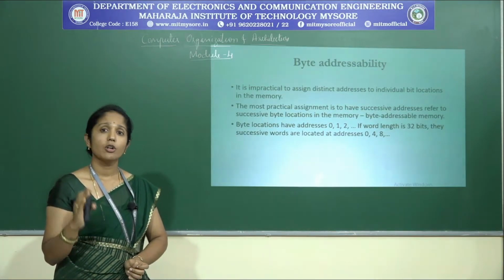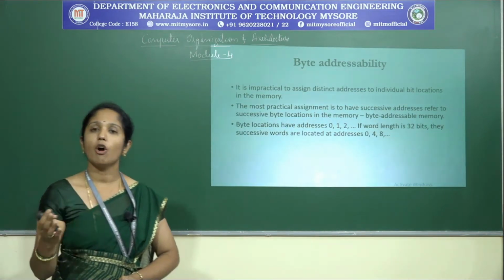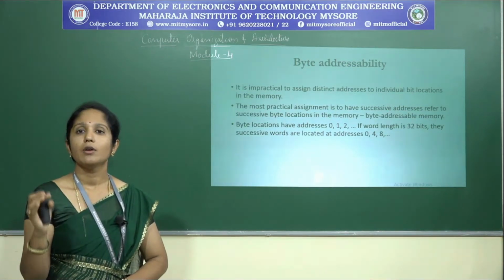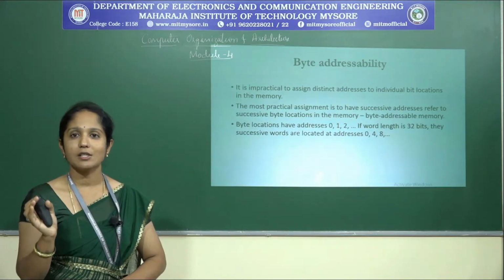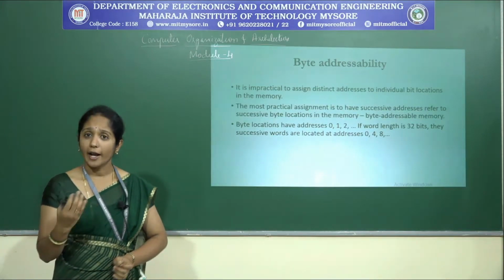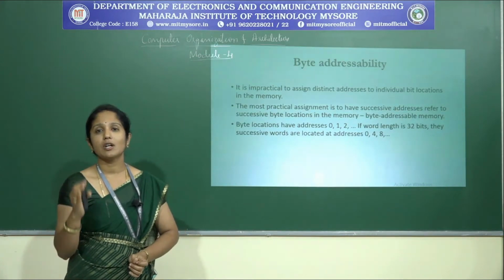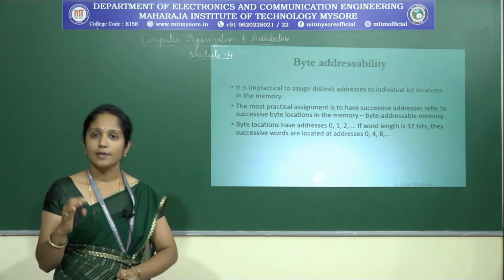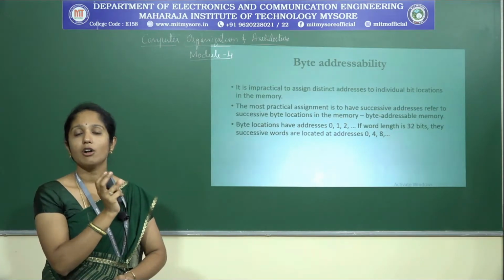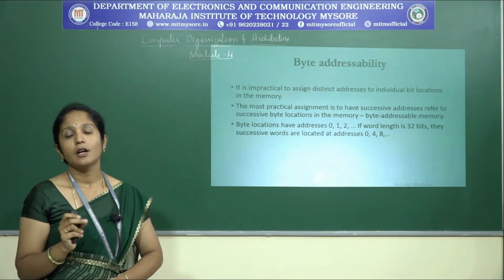If you are performing a read operation, the processor will read all 32 bits, the entire word, and it will consider only the selected byte for the processing. Whereas if you are writing a byte, then the memory control circuitry has to take care that the other bits are not altered except the byte involved in the operation.